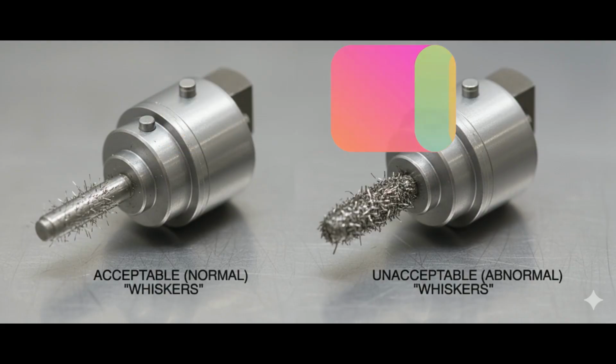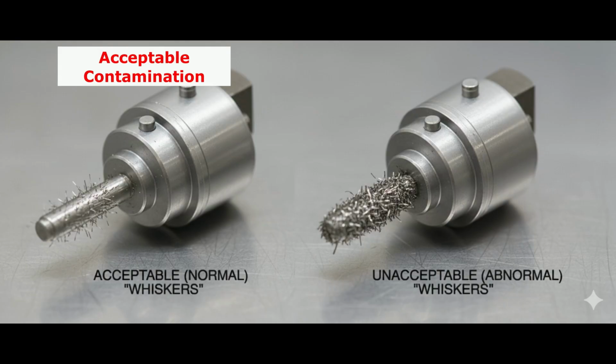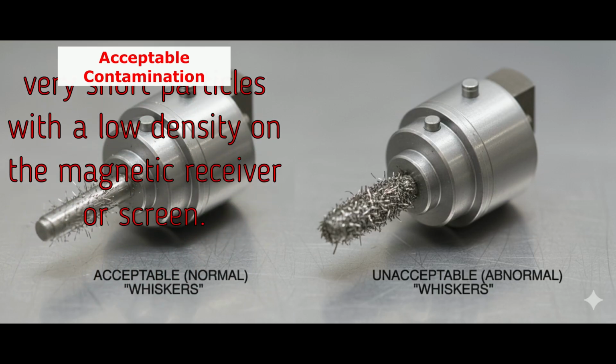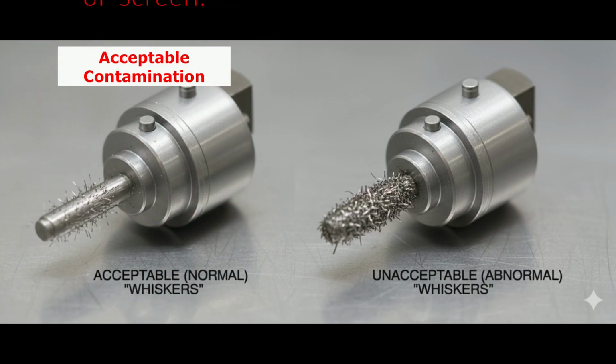Magnetic chip detector and scavenge oil filter contamination limits. The contamination levels on the magnetic chip detector are classified as follows. Acceptable contamination. As shown in the illustration, this consists of very short particles with a low density on the magnetic receiver or screen. This is a normal condition resulting from operational wear.